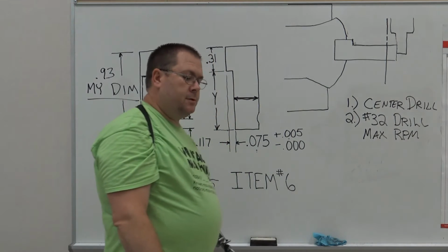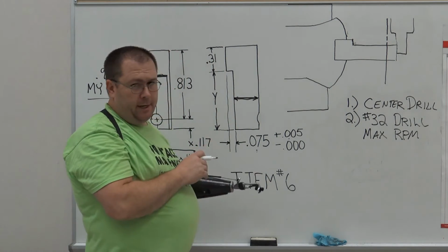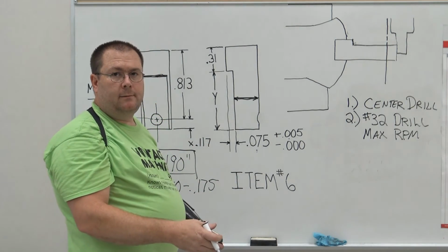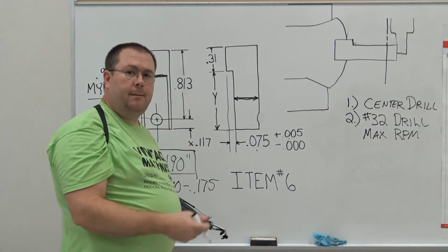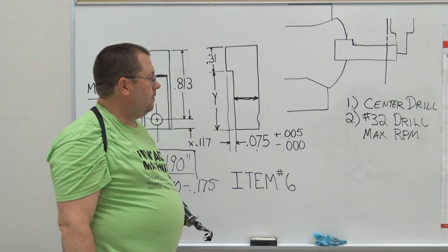Remember, these numbers that we've given you, the cutting speed and the calculations, those cutting speed numbers, as you calculate the RPM, is a good starting point. There's nobody standing above you saying, you have to run this RPM. It gives you a good starting point, okay?